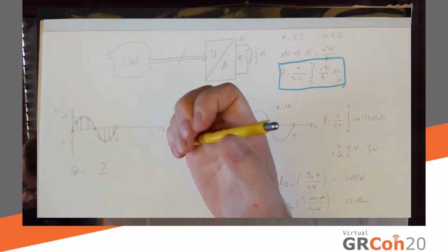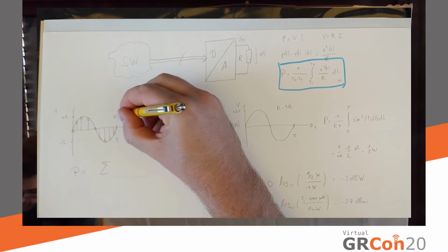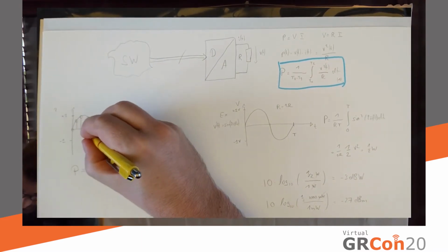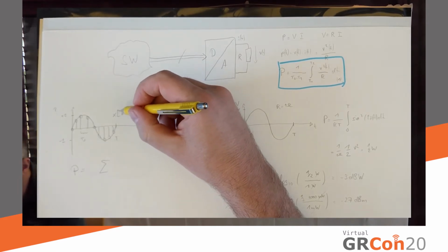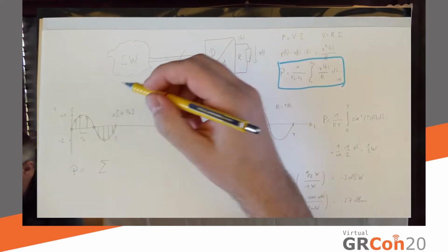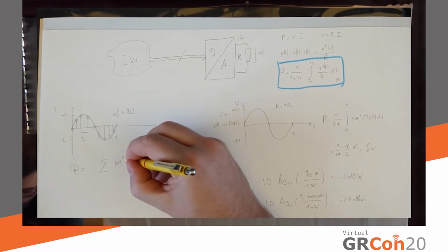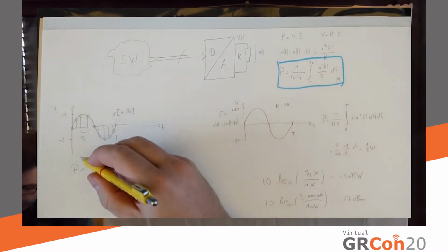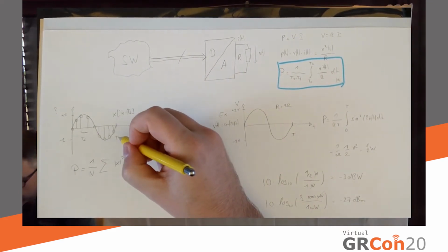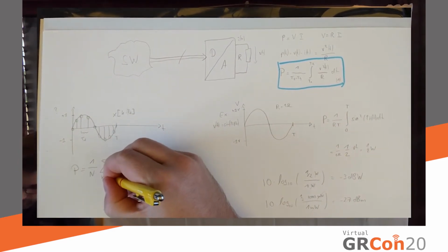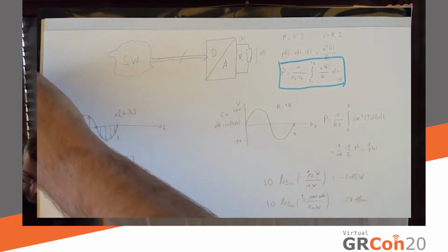First of all, my integral becomes a sum. My signal, I'm going to call it x of k times ts, where ts is the time difference between 2 samples, equals 1 over the sampling frequency. Usually we don't really write it out. So x of k, I'm using square brackets to indicate integer indices, and I'm calling it x instead of v to indicate that this is not actually a voltage. So the modulus of x squared of k, divided by what? Well, this is going to be a number of points. Let's say we're going to integrate over n points, with n times ts equals t. So we say k goes from 0 to n minus 1, and then the average. So average of the square, that's going to be my equation for power on the digital side.